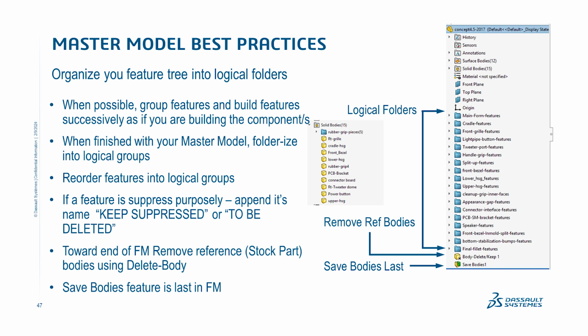So another good practice with master modeling, because you're creating a pretty complex part as a master, which contains many features, is you want to pay careful attention to organization. And when I create master models, I'm pretty freewheeling through most of the process of creating the design intent, but towards the end, when I start to organize it and want to save bodies or insert part, I'll go back and I'll organize my feature tree into features that are common to that quasi part.